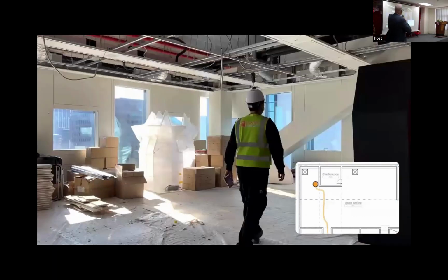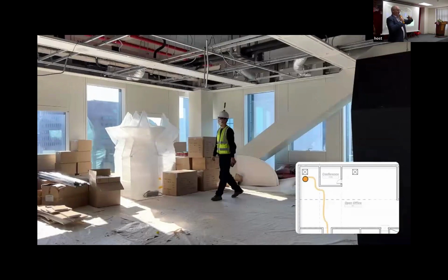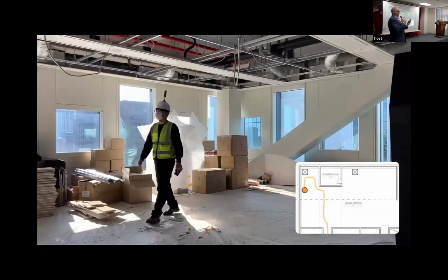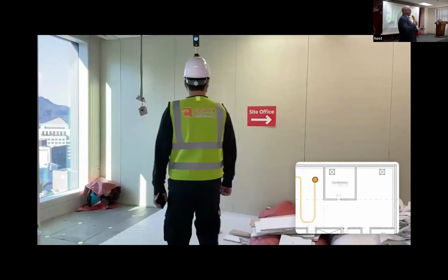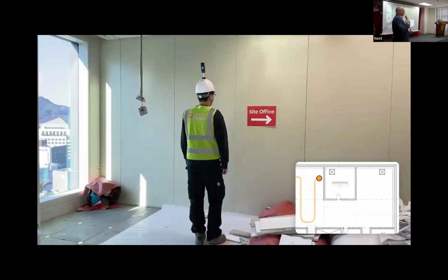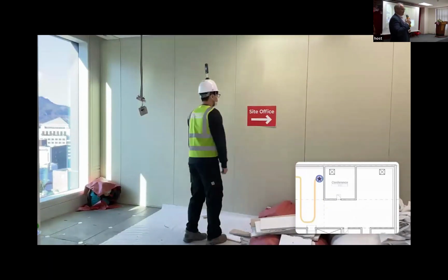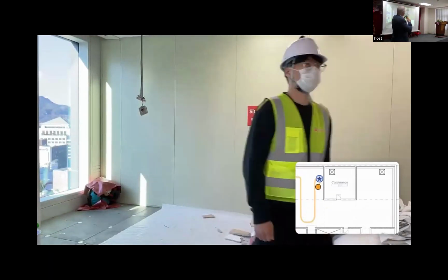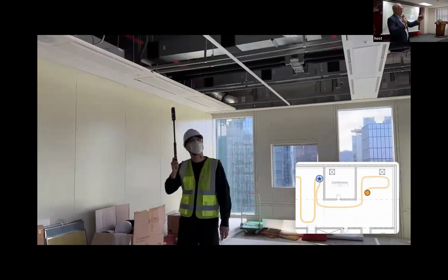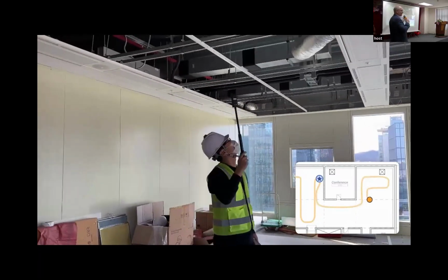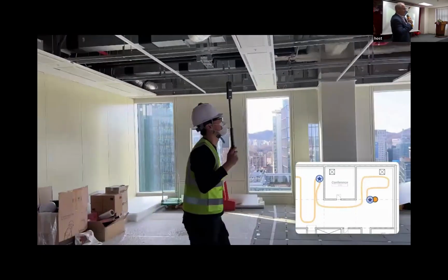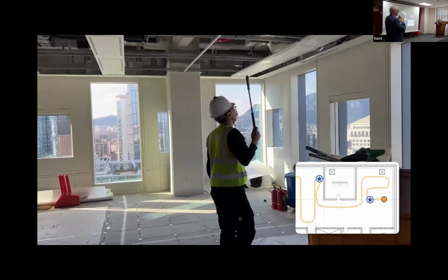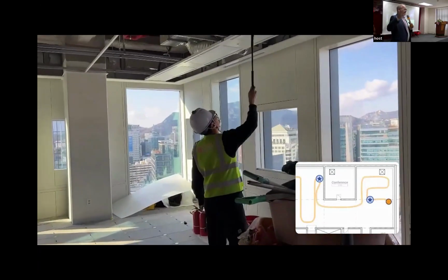You have a camera on the worker's helmet. He's just walking around the project. There is an app on the phone, and the app is tracking their position, so you can see the position on the keyframe. As you're walking around the project, you can be underground, you can be disconnected from the internet, and this will still work. It will record 360 degrees, creating basically a 3D model of your project. You can use it to get into the upper levels, for mechanical checking, for pipe checking. At the end of this process, you have a 3D model of the project.